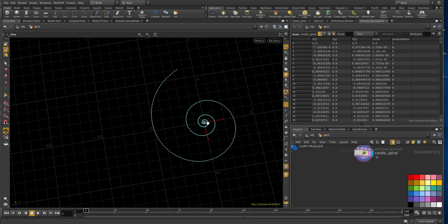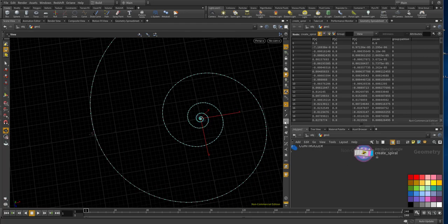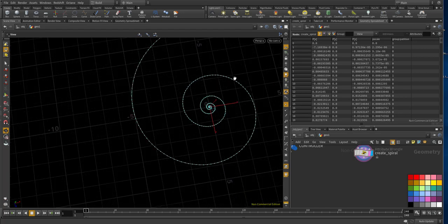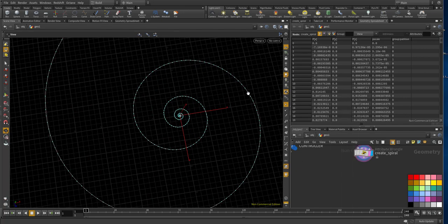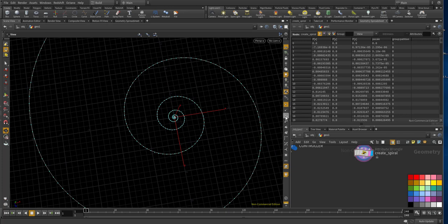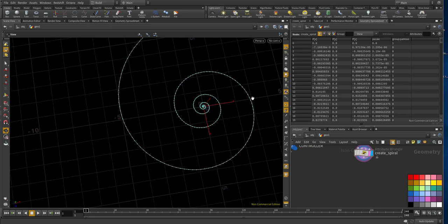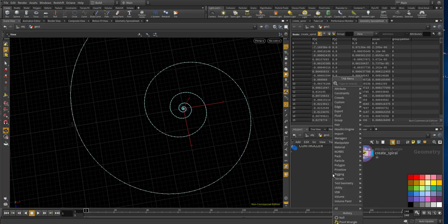So in order to place the partition here, I'm gonna make a partition based on the sphere, but I need to cut the sphere into half so that it will line up with this curve. In order to do that, I first need a normal or tangent vector for each point on this curve. And if you look at this, I don't have any normal value right now, so let's make some poly frame.